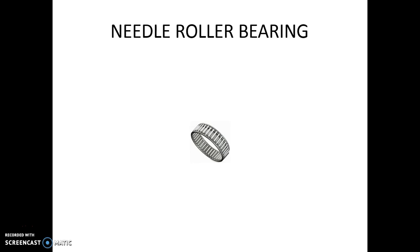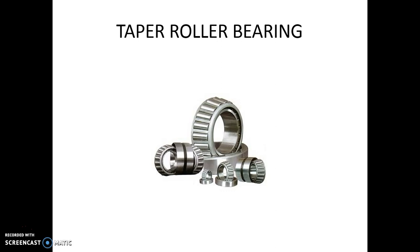Needle bearing: when there is a radial space limitation, we can go for a needle bearing. And taper roller bearing: when you have to support axial load as well as radial load, you can go for a taper roller bearing. This is how the different types of bearings are.